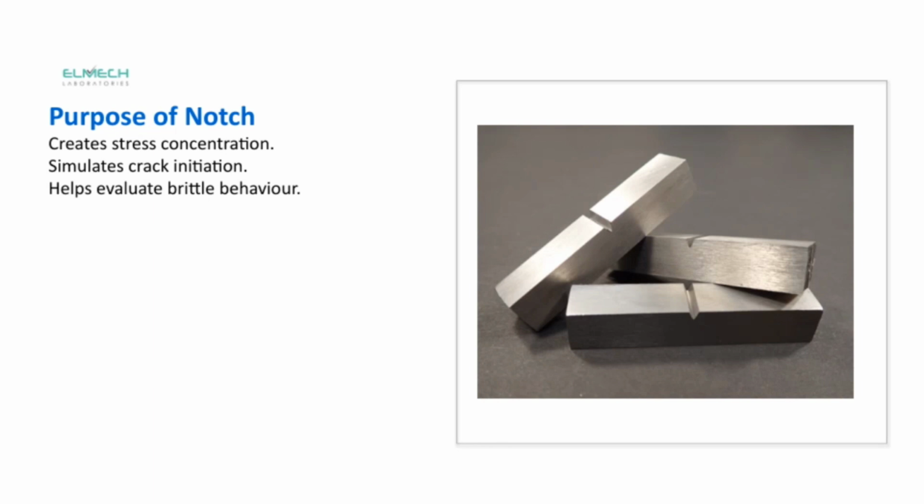Let's talk about the purpose of a notch in material testing. The main idea here is that a notch creates stress concentration. This means it directs the stress to a specific area, making it easier to study how cracks might initiate. By doing this, we can simulate the beginning stages of crack formation under real-world conditions.